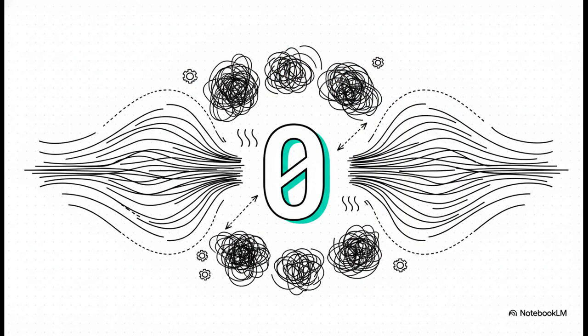Zero. That's exactly what the velocity smoothly decays to as you move away from our oscillating vertical plate. This mathematical zero proves something absolutely vital for design engineers. The intense effects of thermal buoyancy and heat transfer we've been talking about are highly localized to the near wall region. The chaos is all at the boundary; the deep fluid remains totally unaffected.